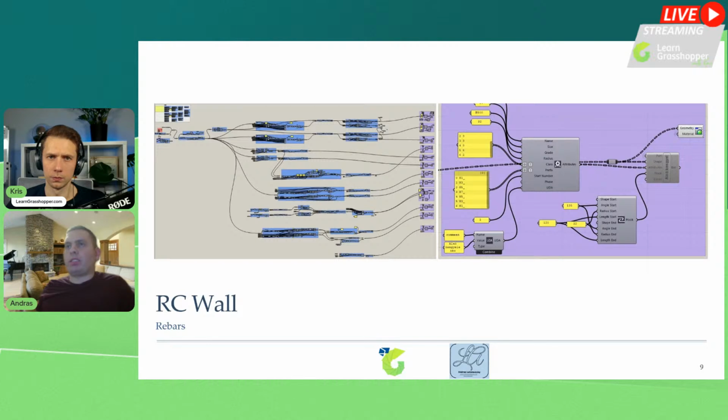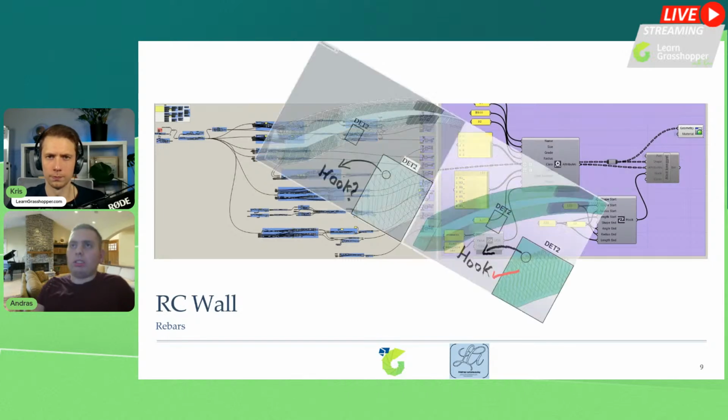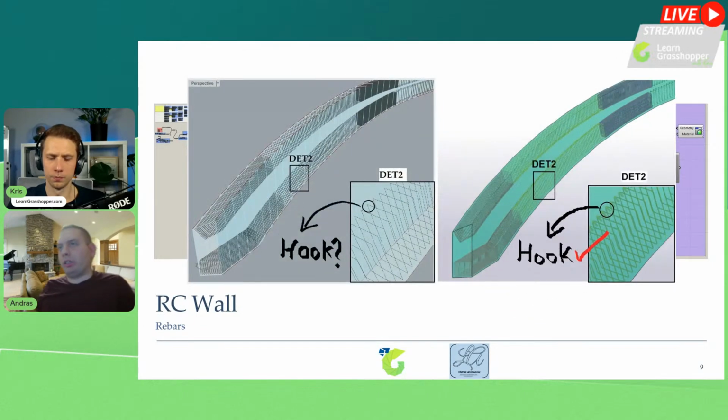The rebar system was quite special. The stirrups, outer, middle, and inner mesh, ball ends, splices, and other rebars could also be added with the code. In Rhino, the geometry appeared without hooks, but of course, I managed the hooks with a Tekla plugin.